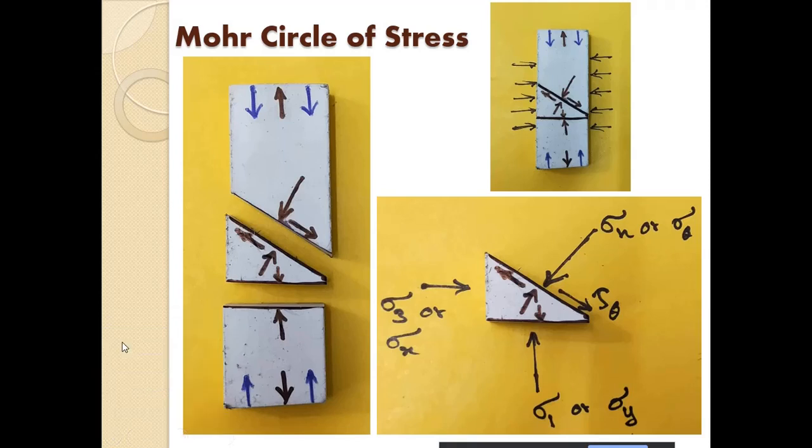Okay, so in the last class we discussed up till here and we saw how the force is transmitted through the sample, and when we have a shear plane, how to assess the forces in the shear plane. So what we do is we take out this triangular wedge, and all the stresses which are acting on it, and then we convert that into forces.